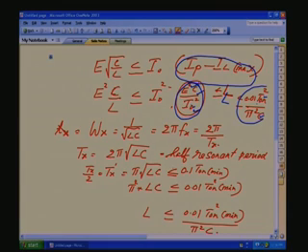So, using simple rules, using engineering approximation, one approximation we said the load is highly inductive, so load is linear. So, from the linear charging or discharging period we have found out the T off maximum or T off minimum required for the capacitor to discharge fully, so that the thyristor will be reverse biased. We found out the C. Then from the repetitive peak, based on the resonant peak and the load current, one condition for L, the lower range, we have found.